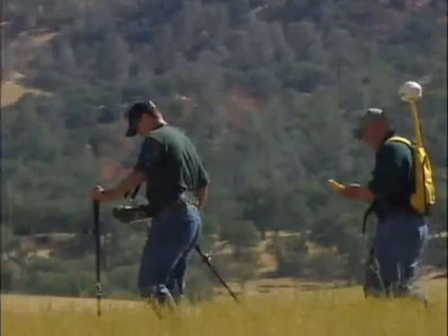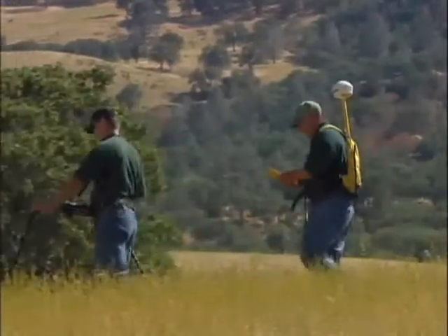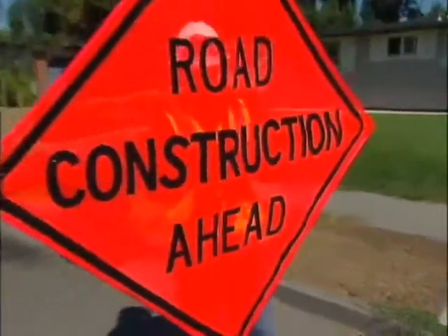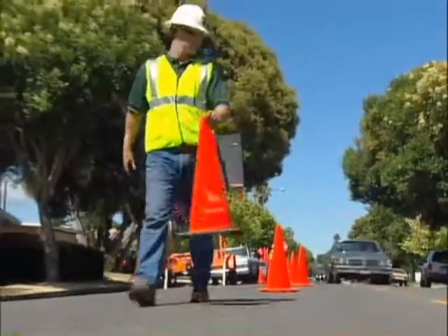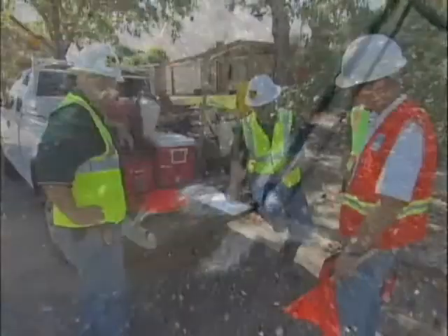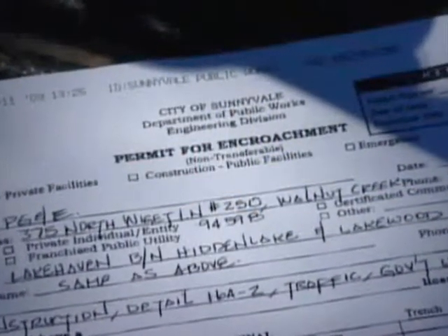For a pipeline that is buried in an unimproved right-of-way, the testing can be relatively easy to accomplish. However, growth has closed in on our pipelines, and testing pipelines that are located in city streets is more complicated. For example, performing CIS in city streets may require traffic control and drilling small holes in the pavement to establish soil contact. Local public agencies have comprehensive permitting requirements for this kind of work.